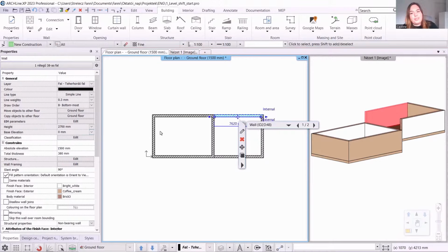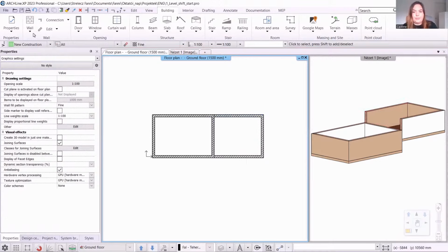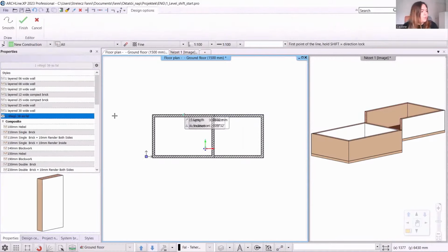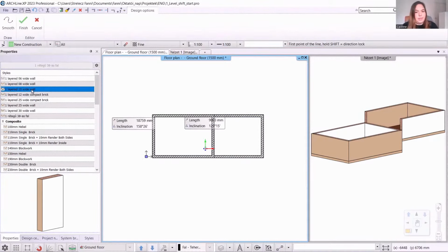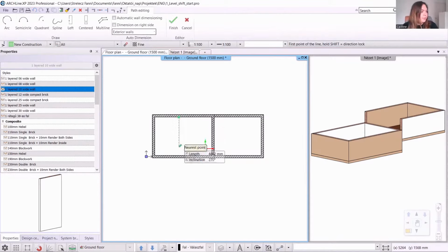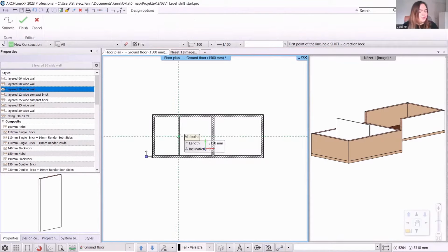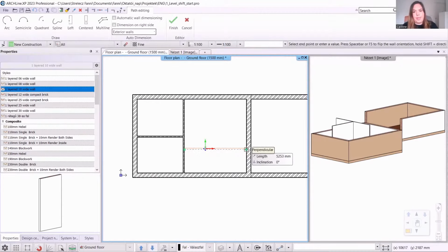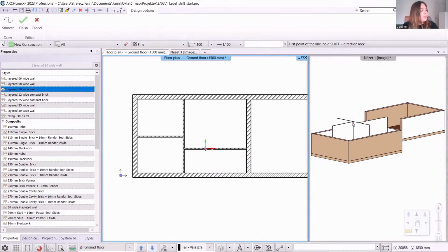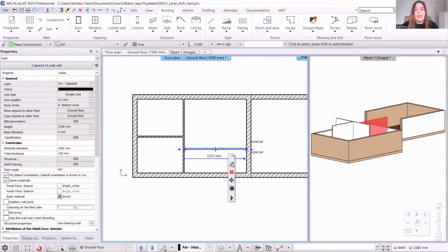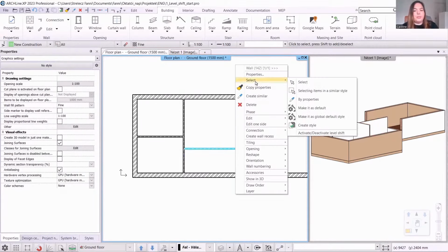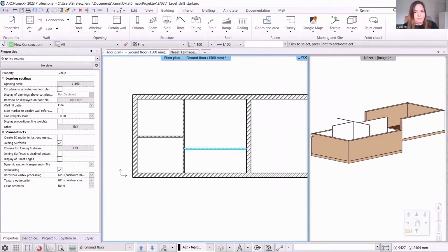Let's see how we can modify the already created walls in terms of level shift. So I'm going to draw some partition walls on the lower slab with the shift enabled. So I draw the walls, and now there are two ways to make this modification. One option is in the local menu here. When selecting an individual element, it allows you to modify them one by one.